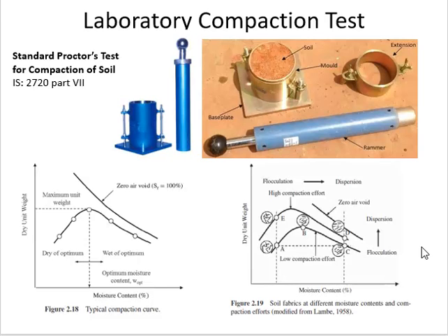So in case of expressways, modified compaction test has to be conducted, where the soil is compacted in 5 layers and the weight and height of fall of the rammer are also more. The maximum dry density obtained by modified test is more than that of standard test, but the OMC is less than that of standard test. The theoretical dry density can be determined when we take percentage air voids as 0 in the dry density equation. When we plot these values, we can get the zero air voids line, which is also called as saturation line.